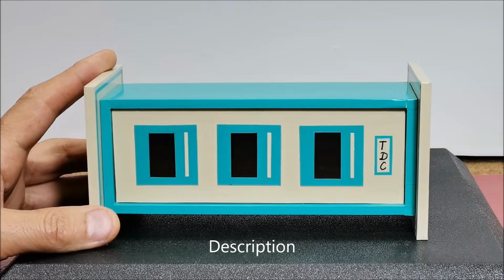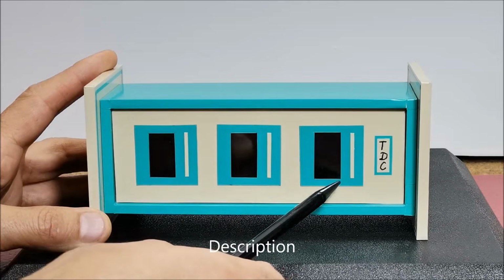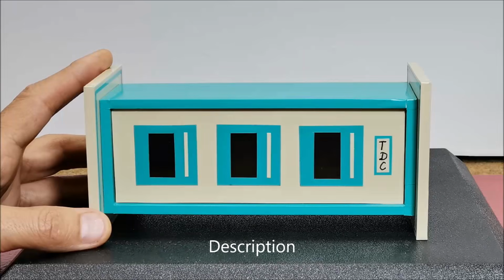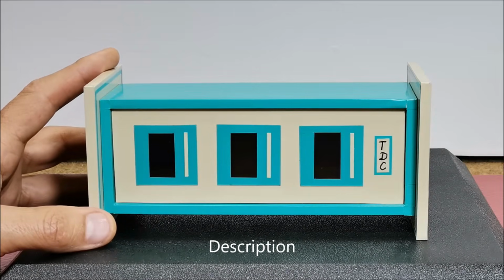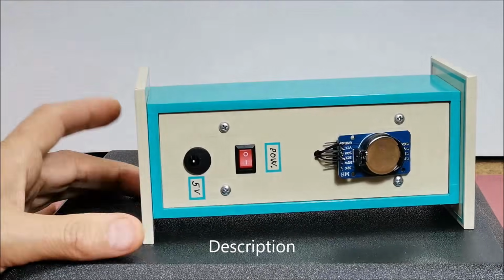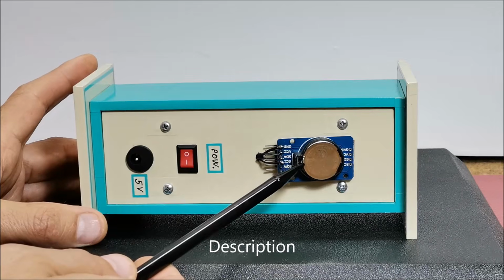Hello, in this video I want to present you another unusual clock to add to my large collection of such do-it-yourself devices. Characteristic for this project is the fact that I used 3 displays on which appears a different content. The 3 displays are with I2C communication protocol and are controlled by a single microcontroller, but with the help of an I2C multiplexer module. I used similar hardware in one of my previous projects, but now instead of a BME 280 module, I used a real-time clock module.